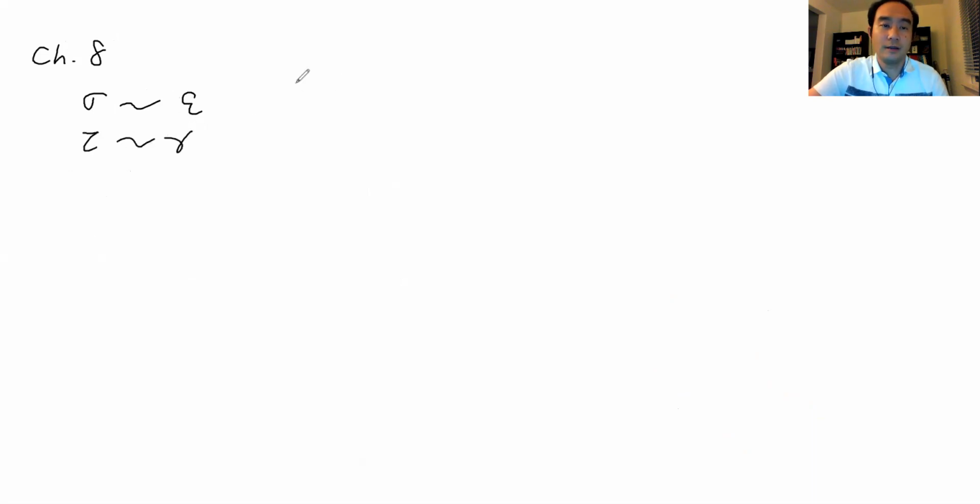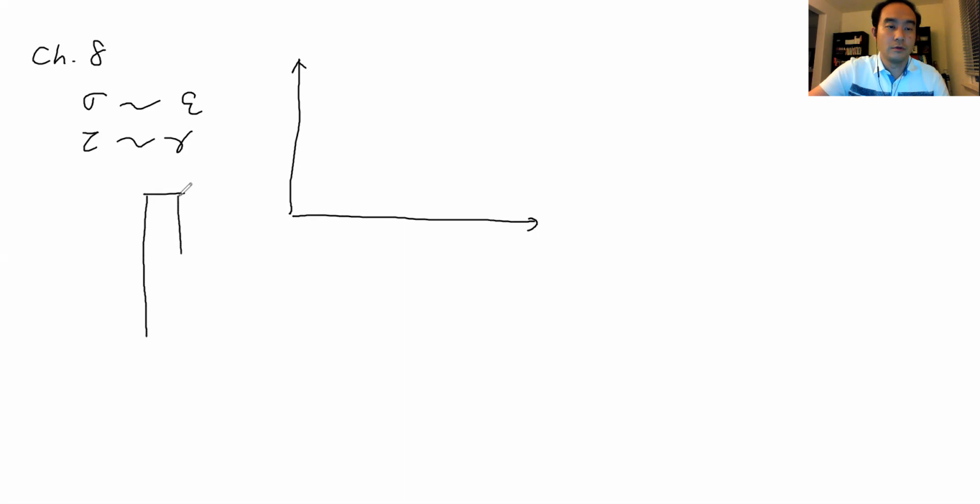How can we see that? The very basic approach is this. For example, here we have a specimen whose material properties we'd like to know. We apply an actual force, the normal force, okay? Let's say that is P, and we can easily find the cross-sectional area before we apply the force. And then we measure the deformation. This is the actual deformation delta.